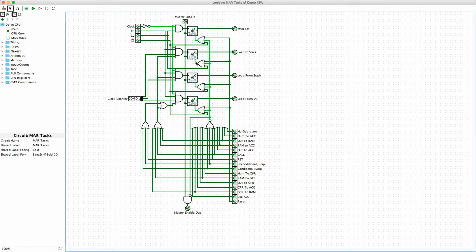I must say, I like Ben Eater's method of using the enable wires a lot better, because the enable wire will simply disable the clock until you're ready to write data to the register, which means these T flip-flops aren't necessary.